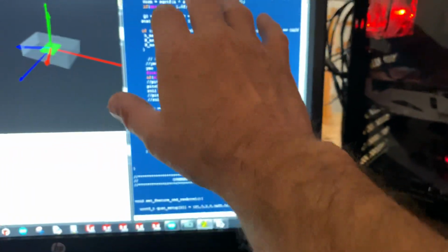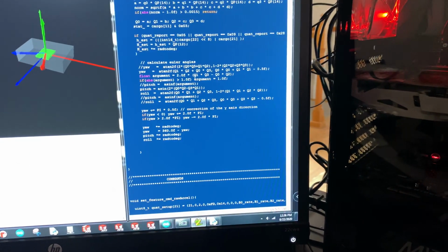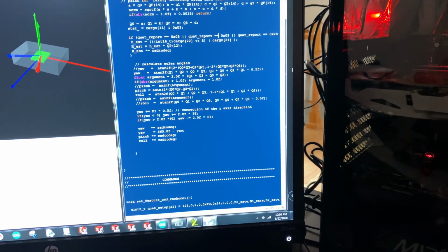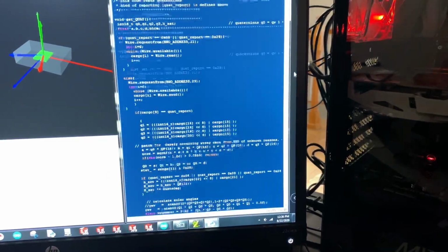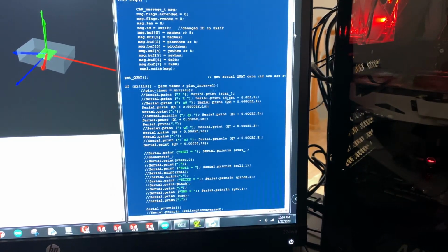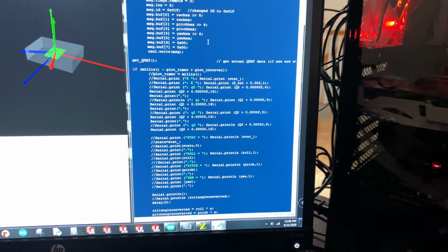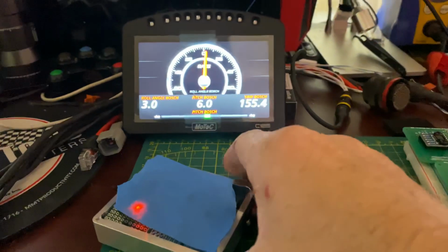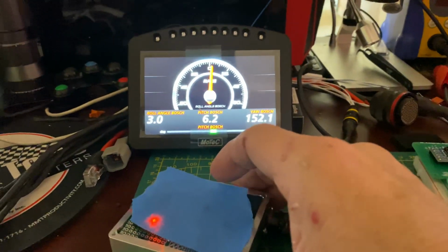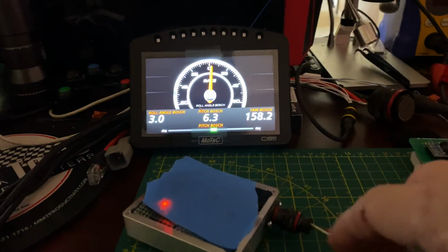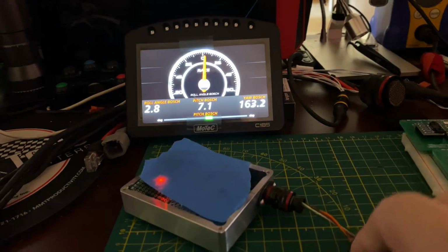So, within this code up here, that's running on a microcontroller, along with what it all else is doing, is creating angles that can be reported, and then it's transmitting them over CAN bus. So there's CAN bus code in here that I wrote that sends messages over a CAN bus. So there's actually a chip in this device that is a CAN chip, and if you send out over CAN, there's some wires coming out of this thing right now. 4 wires.